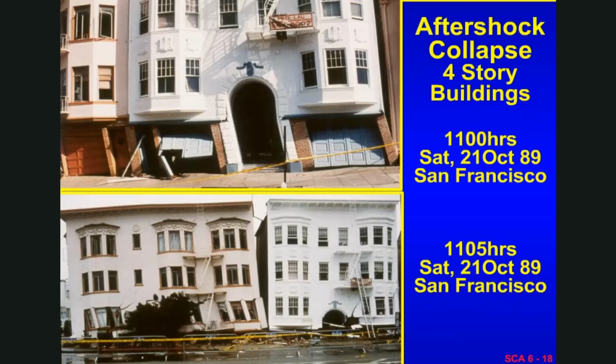This is an example of a collapse that occurred in a relatively small aftershock in the Loma Prieta earthquake. The upper picture is the four-story structure with the garage doors closed that are keeping it from collapsing, perhaps. But following the earthquake on a Tuesday, this is a Saturday, and there was the 5 aftershock, and you can see in the lower picture that you now have 3 stories sitting on the ground, where the second story is at the ground level and the first story is pretty much collapsed underneath it. Very small, very vulnerable structure, very small aftershock, complete collapse.